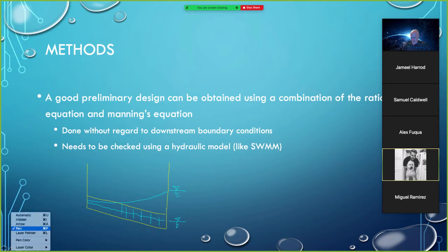And the consequence of that would be, where the land surface, something like this black line perhaps, and I drew it badly, but if we get a portion where the hydraulic grade line goes above the land surface, that's generally not acceptable to us in a storm sewer design.